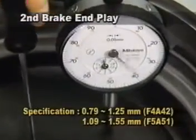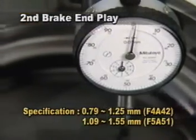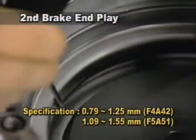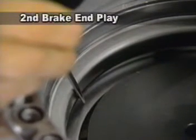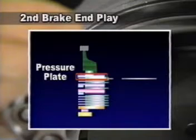If the measured value exceeds the specification, change the pressure plate of the second brake with one of the 8 different plates in thickness. Pressure plate is just below the coil type return spring. To emphasize again, not a snap ring, but pressure plate of the second brake should be changed in this case.